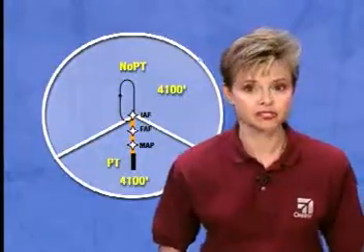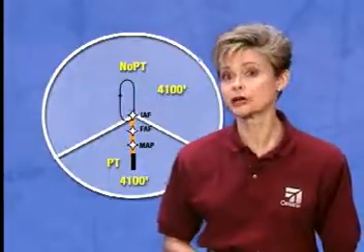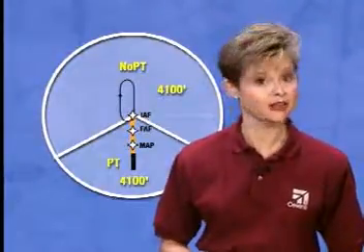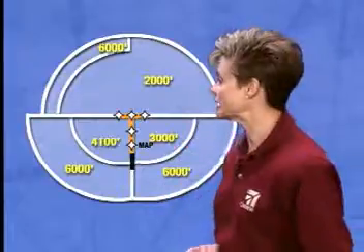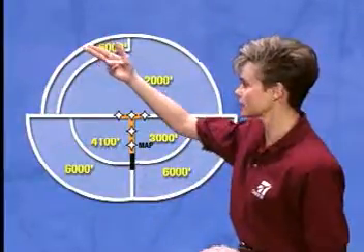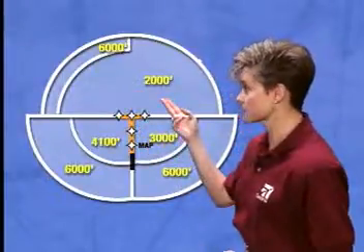You may also see sectors within a TAA showing different minimum altitudes than the area as a whole. In this case, if you arrive from the northwest, your minimum altitude drops from 6,000 feet to 2,000 feet at 22 nautical miles from the initial approach fix. You'll find TAAs tailored as necessary for local terrain and obstructions. Most in Kansas will be pretty standard. On the other hand, those at the foothills of the Rockies may not be.